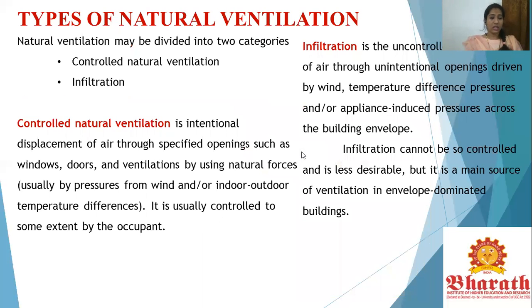Natural ventilation itself is subclassified into two types: controlled natural ventilation and infiltration. Controlled natural ventilation is the intentional displacement of air through specified openings such as windows, ventilators and doors, by means of natural forces.